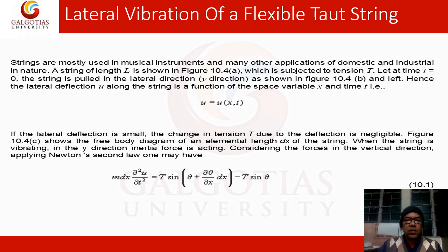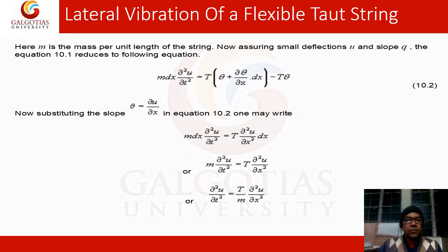Considering the forces in the vertical direction and applying Newton's second law of motion, the equation is written like this: m dx ∂²u/∂t² equals T sin θ plus ∂(T sin θ)/∂x dx minus T sin θ. This is written according to the free body diagram in the previous slide.